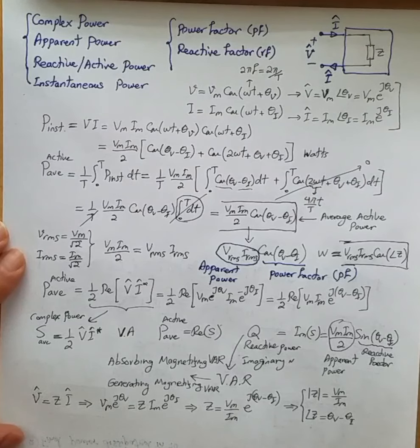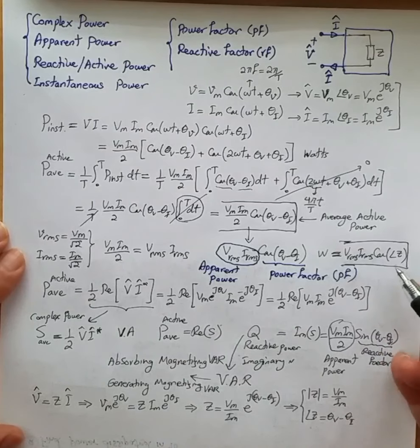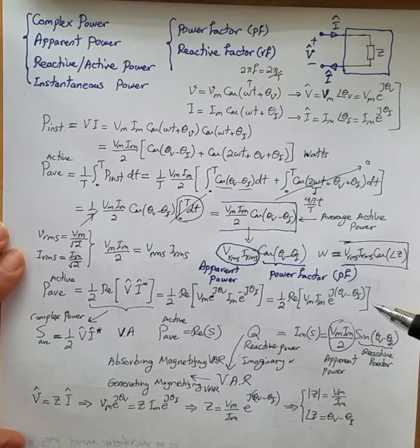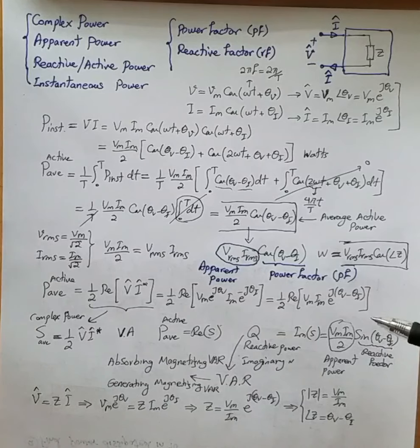And because of that effective inductive load, Z has a positive imaginary part, and therefore in that scenario the phase is positive, and that's why we are seeing a lagging power factor scenario, because current is lagging voltage, again due to the fact that the equivalent load of the system is mostly inductive.